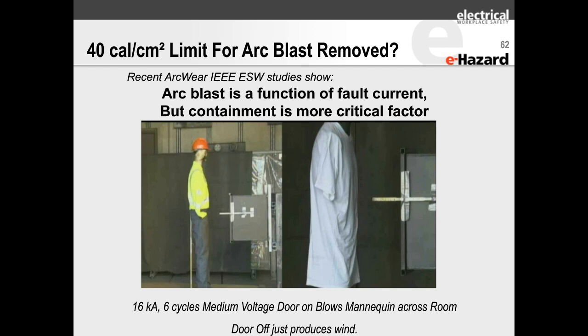We're learning more and more about arc blast and trying to get toward being able to estimate it. When the door's on, the door can blow off. Stand to the side. When the door's open, the blast is substantially reduced to the point where it may not even be anything more than knocking you backward. And we do have video to show what happens, and we'll show that at that Electrical Safety Workshop.